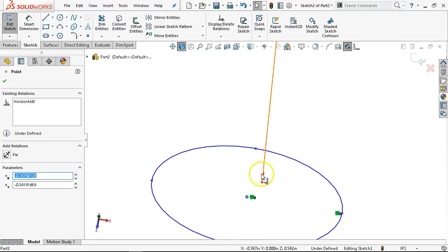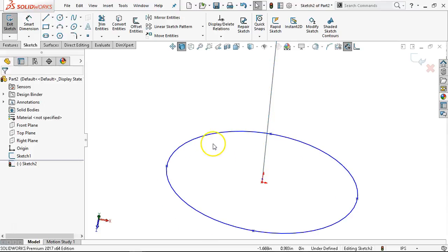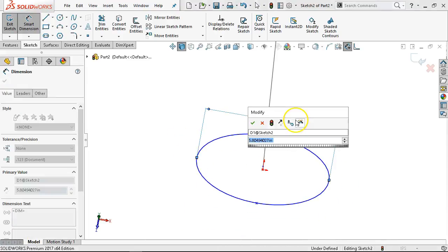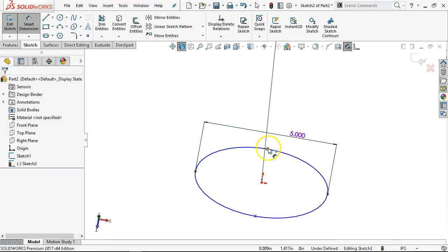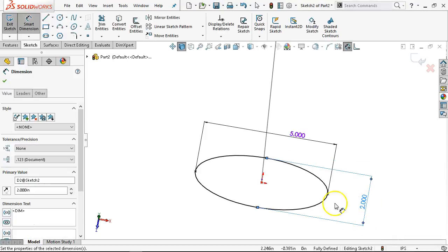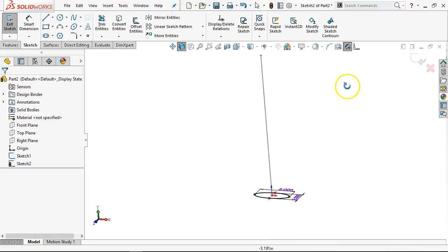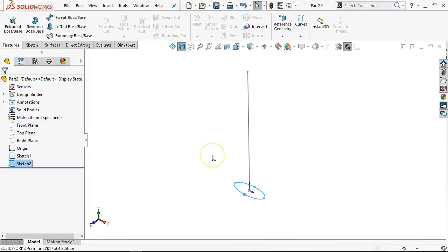When we're piercing, pierce is still going to be preferable. Again, I don't know that it's necessary, but pierce has less failures than trying to make things coincident. So we're 5, and we'll make it kind of narrow. Go to 2. So for the SolidWorks example that they use, they actually do a curve through points, and I should try and find that file.